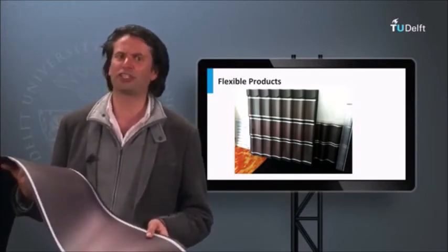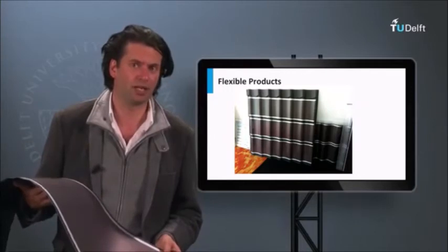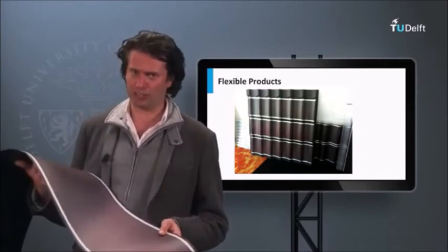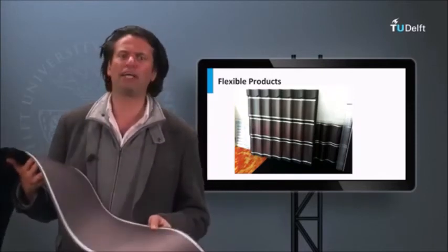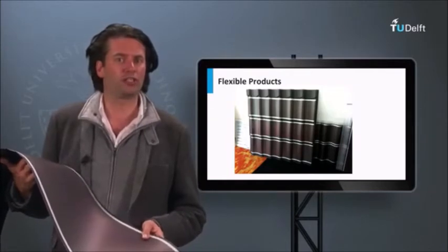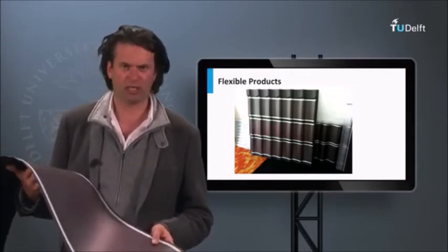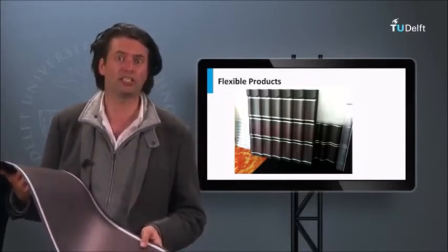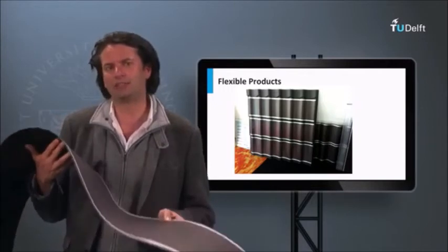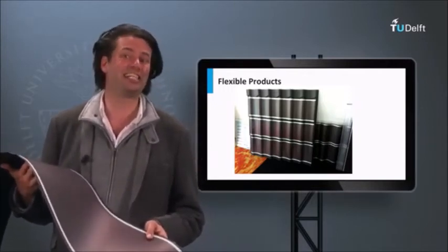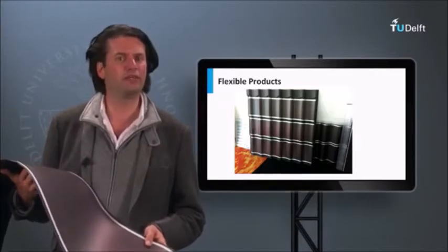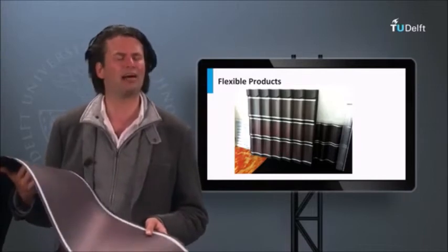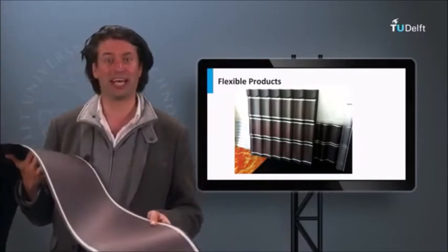This was the quick introduction into thin film silicon PV technology. In view of time limitation, I did not talk about thin film silicon junction crystalline solar cells. These are based on thermal crystallization of amorphous silicon deposited on non-wafer based substrates. On lab scale, close to 12% conversion efficiencies have been achieved with this approach as well. In the next block, I will talk about CIGS PV technology. This is the thin film PV technology which has the highest achieved efficiencies on both lab scale and module level. See you in the next block.